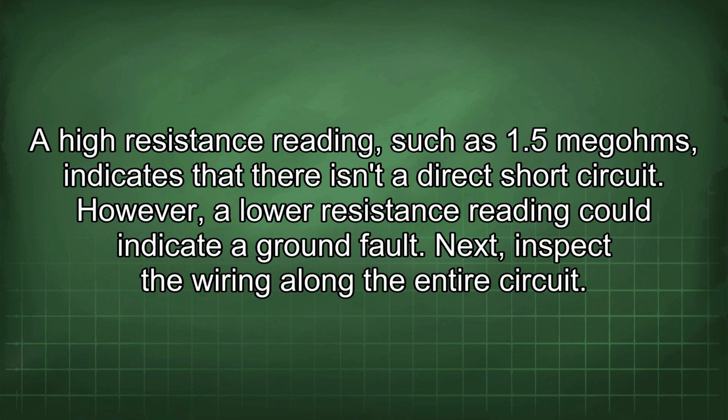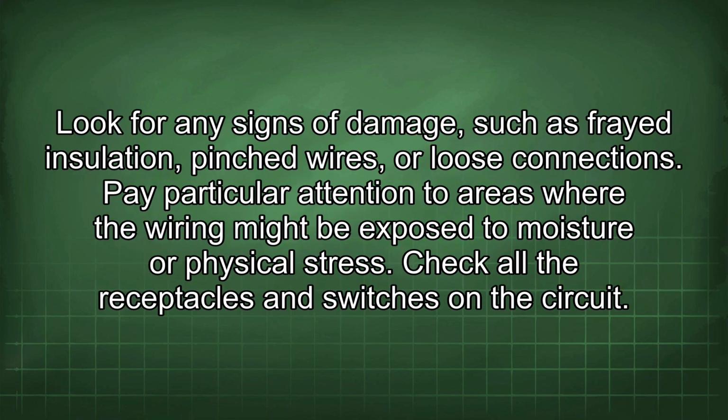Next, inspect the wiring along the entire circuit. Look for any signs of damage, such as frayed insulation, pinched wires, or loose connections. Pay particular attention to areas where the wiring might be exposed to moisture or physical stress.